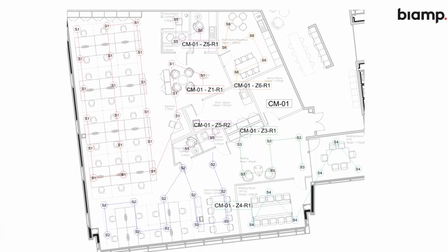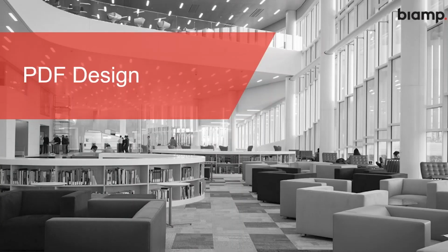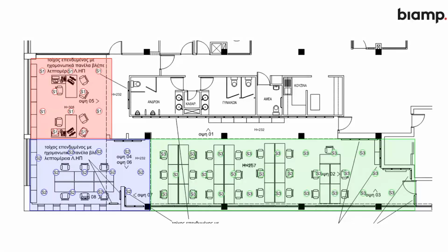You can also use PDF. If we do it on PDF, personally, I use Bluebeam, although any PDF writer can be used. And following a similar format, get a scale off the drawing somehow. In this case, we had to use the door. And we could lay out the emitters like so. Now, what you might notice on here is that the emitters are not following an exact grid. This is because of the size of the space where we have to put two in the middle to keep the uniformity.